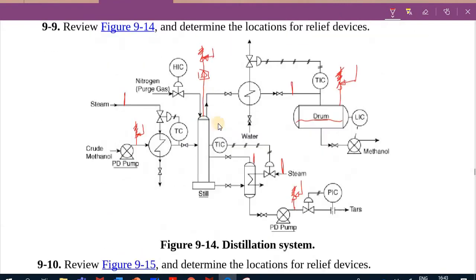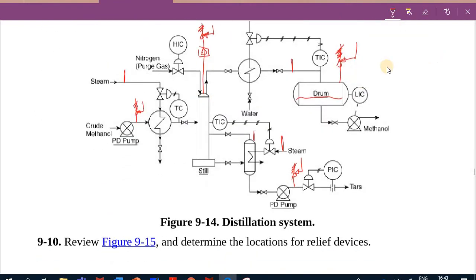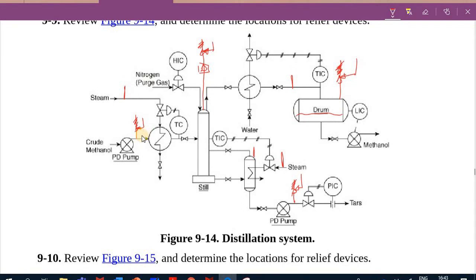So going back here, what type of relief valves should I use? Well, if here it's a liquid, right? So a relief valve, definitely. And here's a liquid relief valve, definitely. Here we have both, so we can use a combined one, so it would be the safety relief valve, right? And for the steam, it could be a safety valve, definitely.